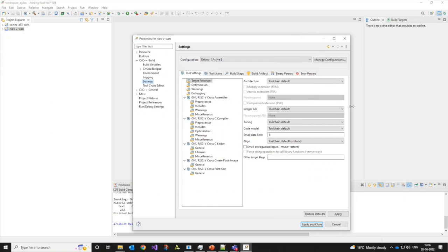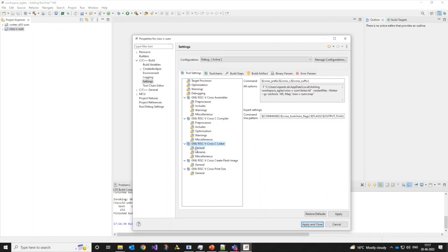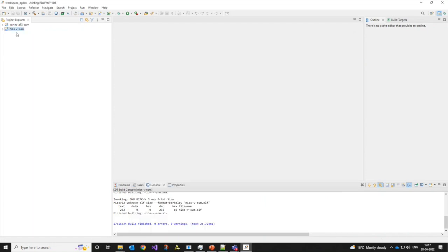So by default, we have some sensible defaults, but all of these, the compiler settings, compiler flags, linker flags, everything can be overridden from the properties page, as I just now took the compiler options, the linker options, the linker file, all these options can be changed here. Okay, so coming back, we just build the application right now.